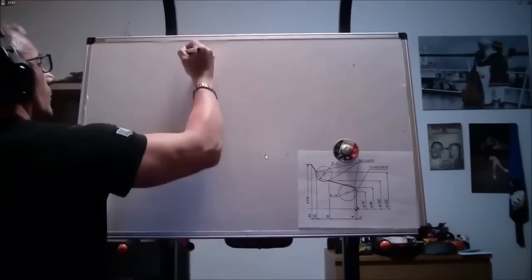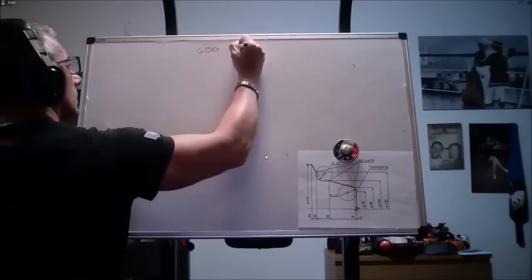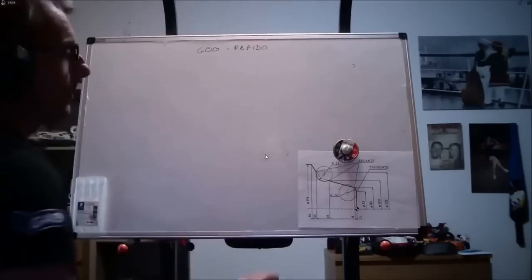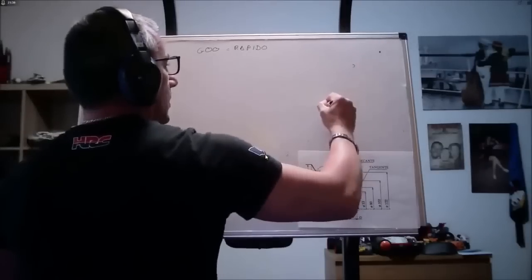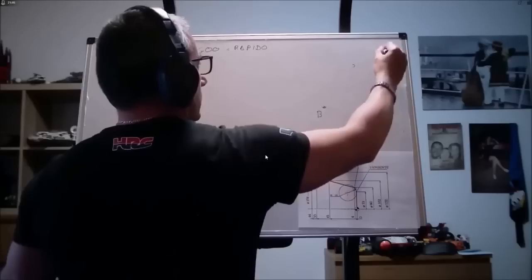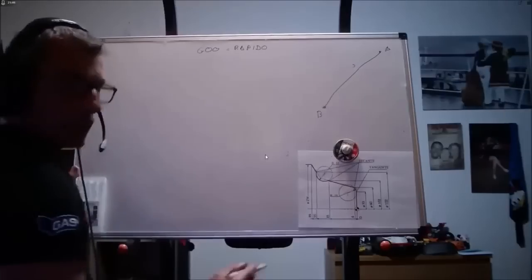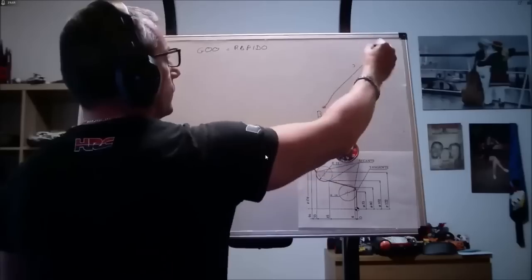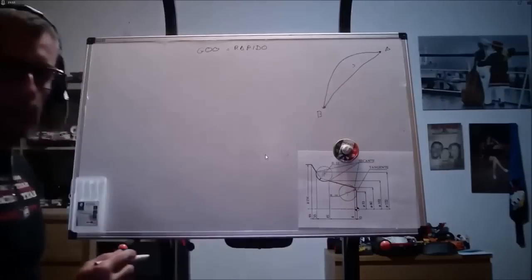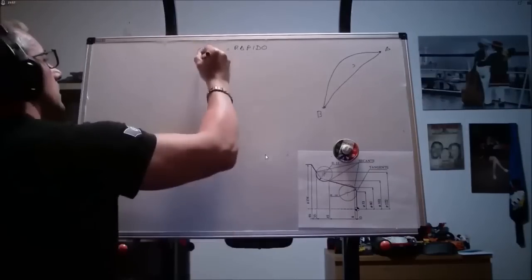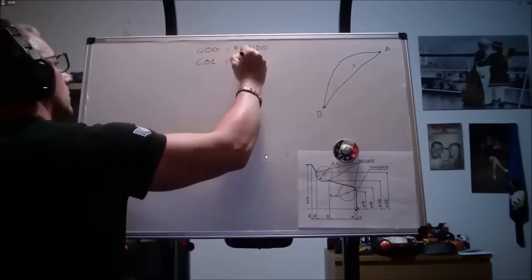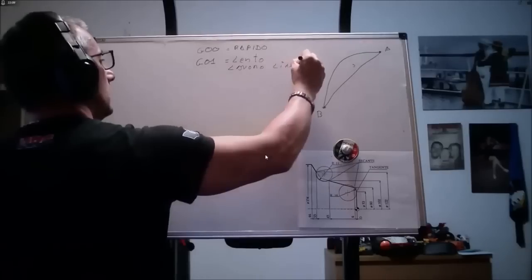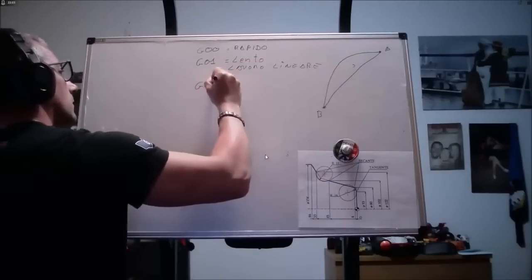So let's recap. G00 is fast movement: some machines will execute fast movements from point A to point B along the shortest trajectory, while others will bring the axes to maximum speed, and depending on whether the distance is greater in one direction or another, they may follow different trajectories. G01 is slow working movement, such as linear moves. G02 is circular interpolation clockwise.